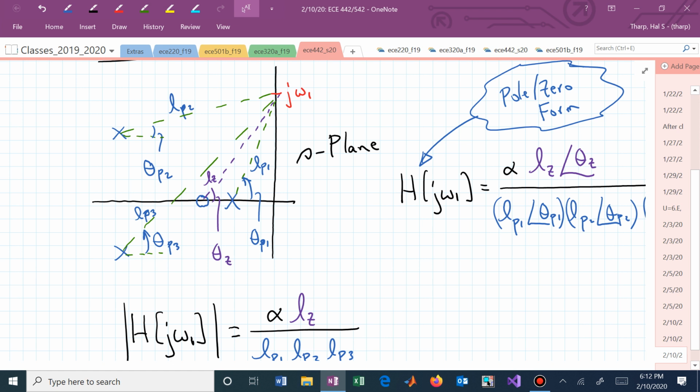I'm assuming I have linear factors. I have 3 poles, so that gives me minus 270. I have 1 zero, that gives me plus 90. I combine those and I end up at high frequencies at a phase of minus 180 degrees. I think that's what you're asking. So at high frequencies, you will be at minus 180. At low frequencies, what are you?